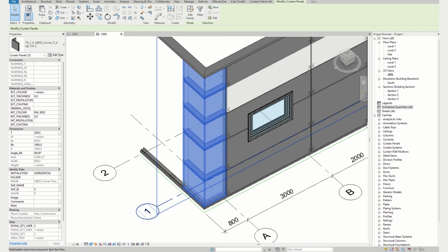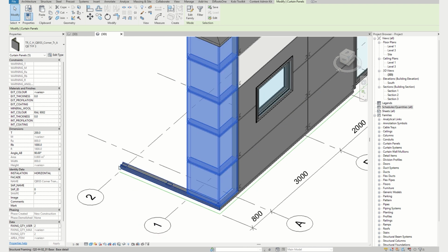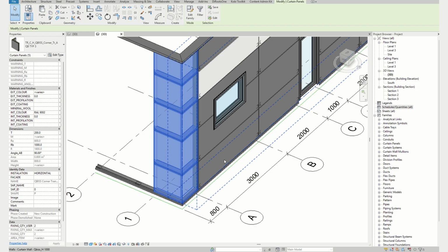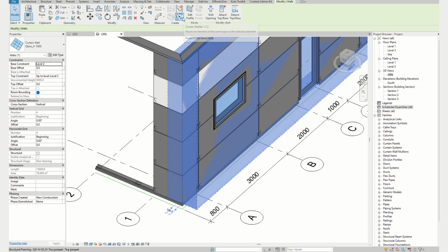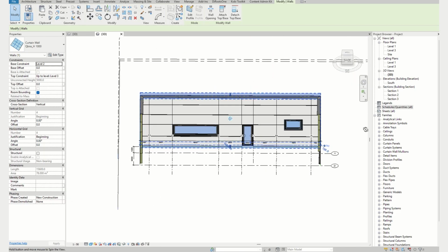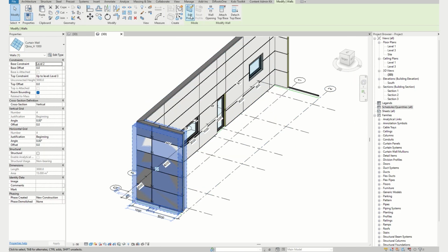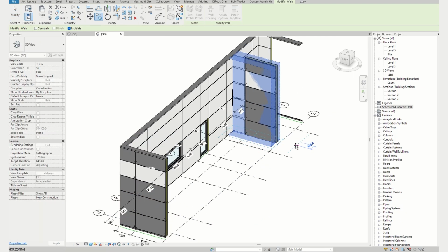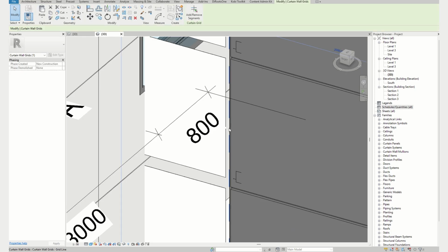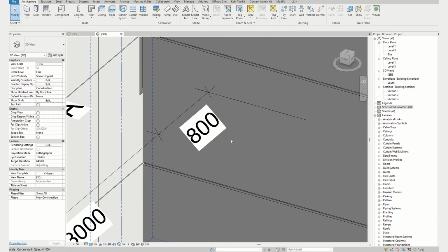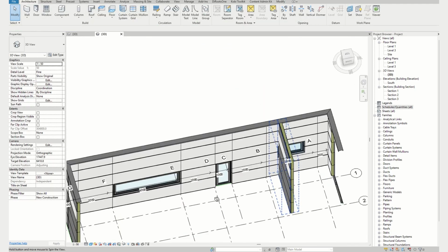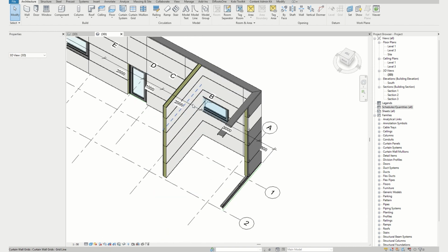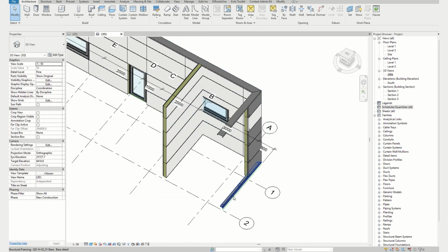And now we should create new wall in here. We could use the create similar command and place wall here, but there is a faster way. Let me copy this part of the wall here and let me delete this grid. We will rotate this wall to this position.